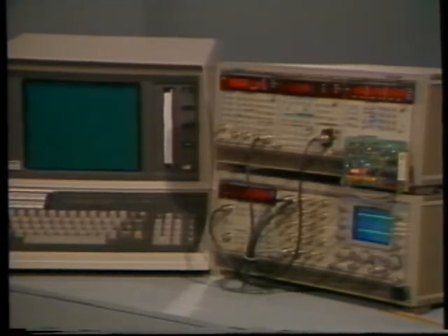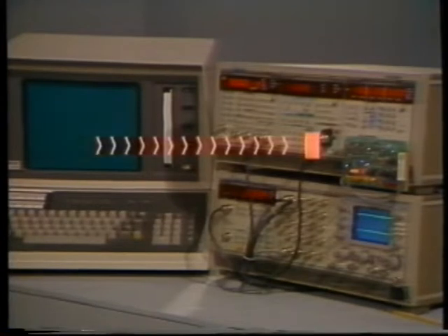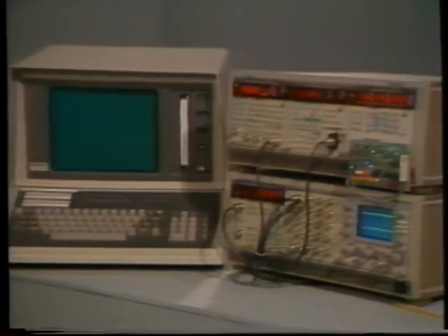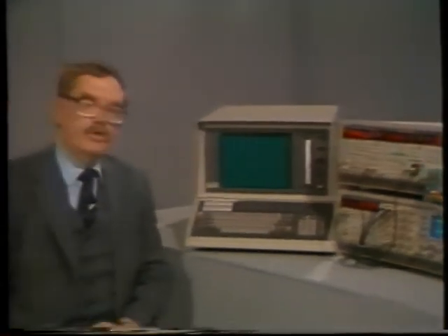In a serial poll, the controller addresses the instruments on the bus one at a time, asking each if it asserted the SRQ line. When it finds that device, it extracts a status byte from the device which tells what the device wants. Extracting the status byte also causes the device to remove its assertion of the SRQ line.